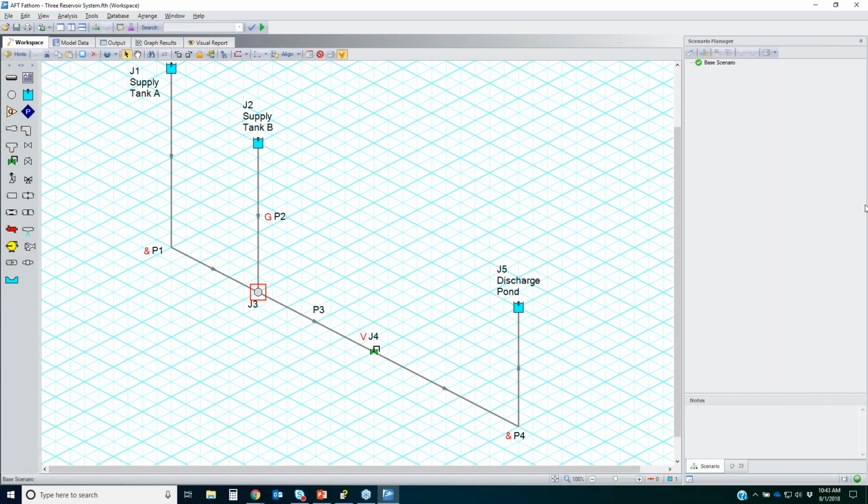You've got flow going downhill. The flow is going down in these two pipes. So when your flow is going downhill, you've got a hydrostatic component that is helping regenerate pressure. So rather than having a pressure loss in the pipe, you actually have a pressure gain. So the pressure right here and right here is higher than the pressure here and here. Simple hydrostatics. So Fathom is taking that into account, all of your standard fluid mechanic principles. It's not doing anything magic.